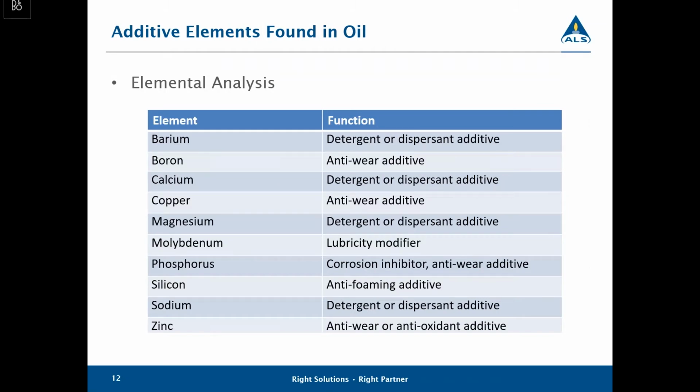Additive elements is another way that we can ensure that you're using the correct oil. There's many out there that change their own oil, and so they know exactly what they're putting in it. Others might have a maintenance group doing it. But if we're told what oil is in that engine, if it does have an additive package, we can compare that known additive package levels to the oil that's in your engine to ensure that you have the right product.